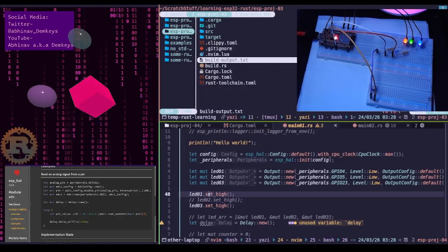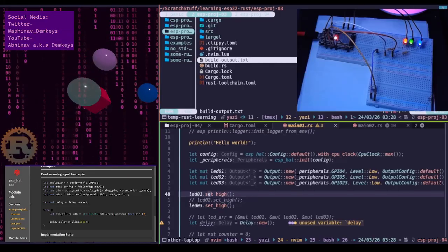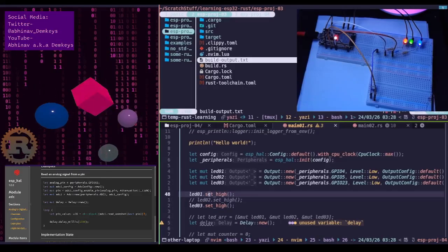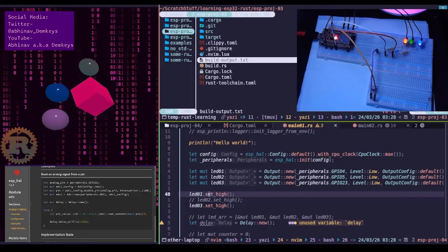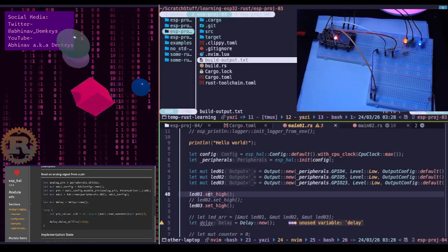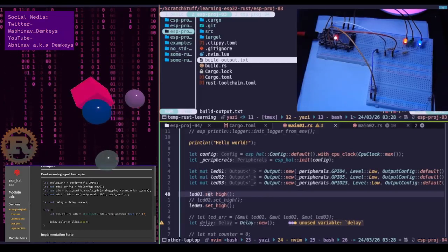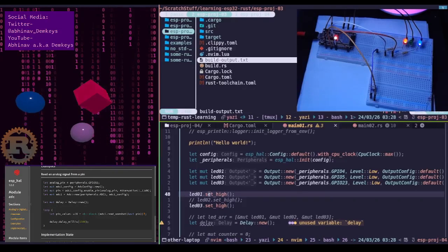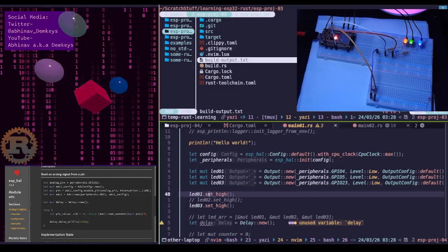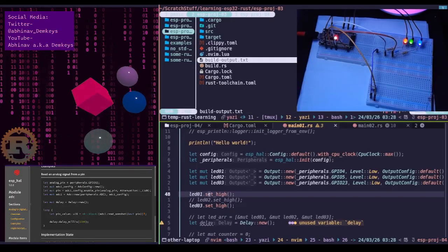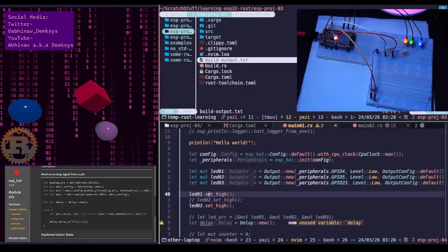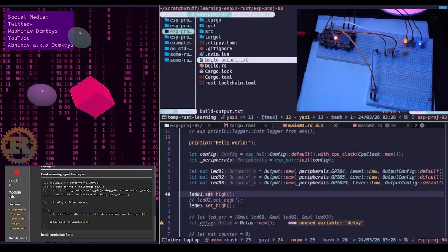But with the single core wire, I've been having trouble getting the heat to transfer very well, and also I've been having trouble getting the solder to stick on there. It has a weird behavior when you try to melt the solder onto it. I still haven't figured out exactly why that is.